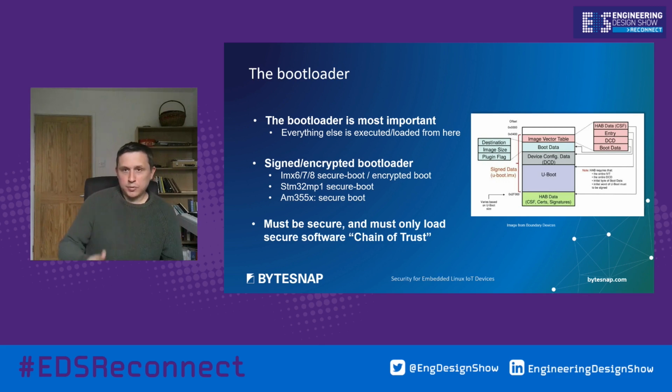So secure boot doesn't necessarily mean that you can't change the software on it. It just means that whatever you change it to has to be signed. That's a bit of a common misconception, but it also applies to boot modes. So if you're booting off SD card, you can still boot via USB with secure boot enabled, as long as it's correctly signed. That's the key point.